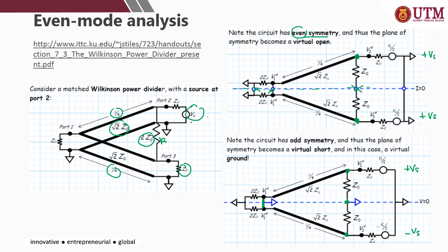The complete derivation for the even and odd mode is shown here. You can just read through or follow the processes involved in order to get the complete S matrix, or S parameter, for the Wilkinson power divider.